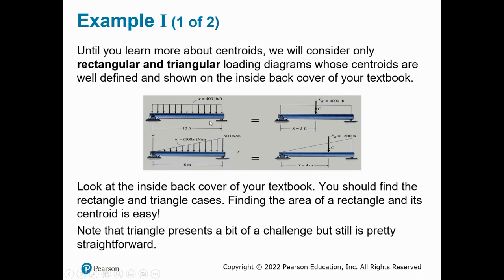To replace this distributed load with one single equivalent force, the location will be right in the middle of the rectangle. Overall I have 10 feet, so the equivalent force will be at 5 feet.